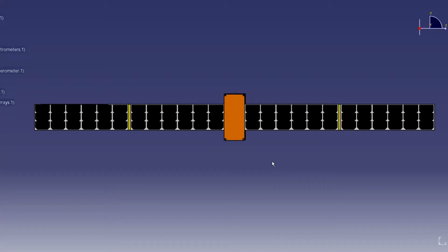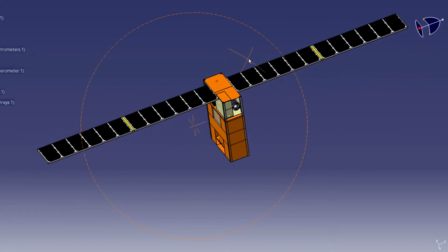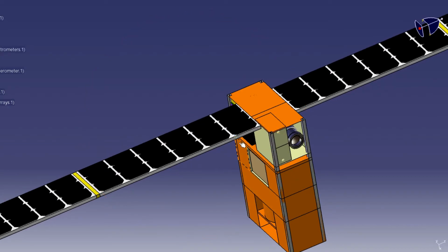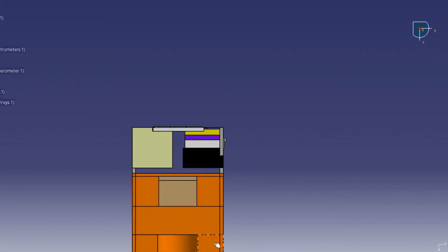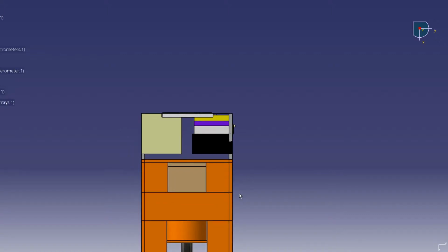Now, about the solar arrays. The panel-mounted approach tracks and points the solar array to get the best sun incidence angle. It has 72 solar cells. Inside the satellite, there are gimbals that fold the solar array in order to join them to the satellite's external structure. The solar arrays also need to be placed away from the payload, as shown here, and other spacecraft subsystems because of the high temperatures of the solar cells.